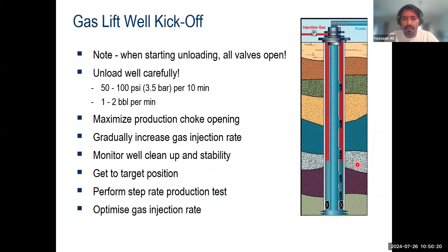Number one is that, specifically for the subsea and deep sea application, one of the constraints is that the cost of intervention is just too high. It's very expensive to change the valves. It's very expensive to move the rig. So one of the challenges is that when you are designing a subsea well, you have to think about gas lift from the very start of the planning or the very start of the project. It cannot come later in the project.